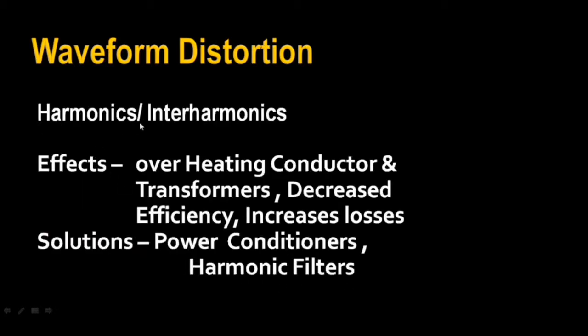For interharmonics and harmonics, the effects are overheating of conductors and transformers, decreased efficiency, and increased losses. And the solution, in order to reduce these quantities, is power conditioners and harmonic filters.